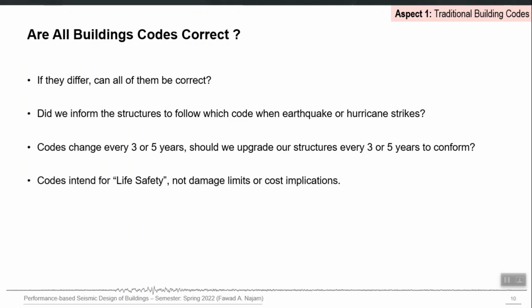And then one more thing which I want to highlight here is that building codes always allow alternate procedures. This misconception that performance based design is somehow against building code design philosophy is not correct, because every building code contains an escape clause, mostly found in their first few chapters. In the starting chapter, or the scope section of a particular building code, they always mention that if you have some other alternate design philosophy which you can justify, which is more advanced than the code's design philosophy, and you can get approval from the authority having jurisdiction at your site, you are allowed to go for that option, right?